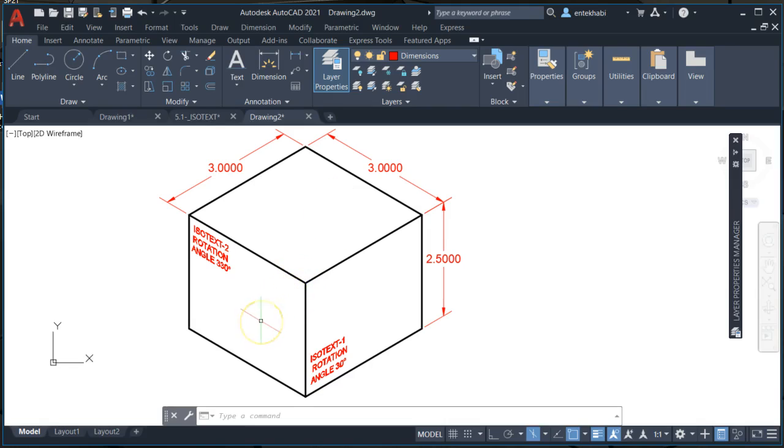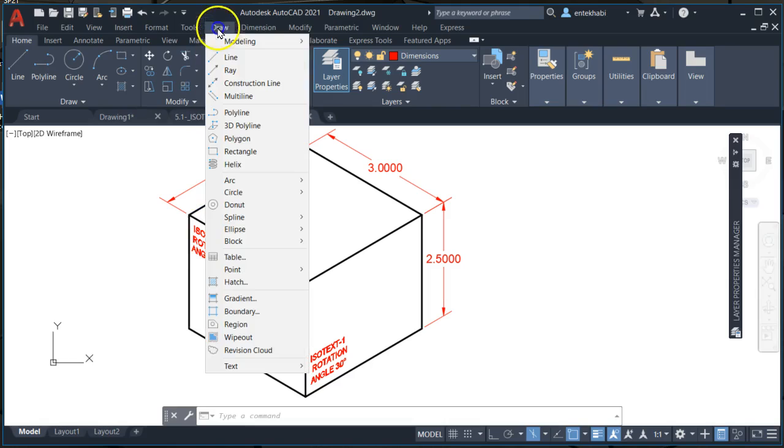So at this point I'm going to show you how to create those holes on each plane. For isometric, we have learned in basic drafting, when we were using the T-square, templates and other manual drafting methods, that holes in isometrics are not drawn using a circle. It has to be an ellipse. And there's a special kind of ellipse for drawing in isometric, which is called the iso ellipse. AutoCAD provides that option easily by going to Draw and selecting Ellipse.